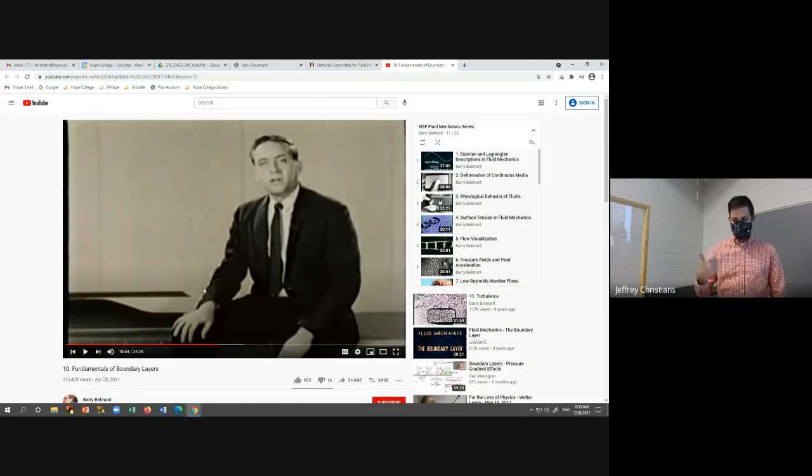It's the velocity. I've called it U infinity. That's the term that we'll use for this free stream velocity, like the velocity far away from everything at infinity. L, the distance along your plate, divided by nu, viscosity divided by density. We're going to relate these by what we call the Prandtl number, which is a ratio of the kinematic viscosity nu and alpha, which is the thermal diffusivity.